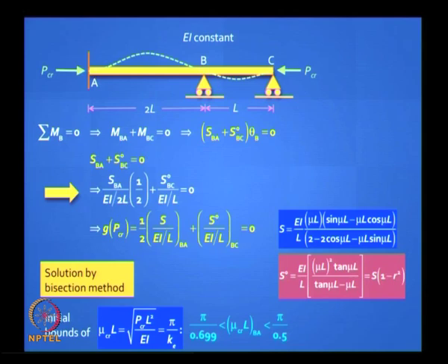It is LE squared for any set of boundary conditions. So it is very convenient. You identified 0.699 and 0.5 for element BA, and for element BC can we still use BA? Yes, we can, because the two spans are related. For the second element it is half the value as that of the first element.